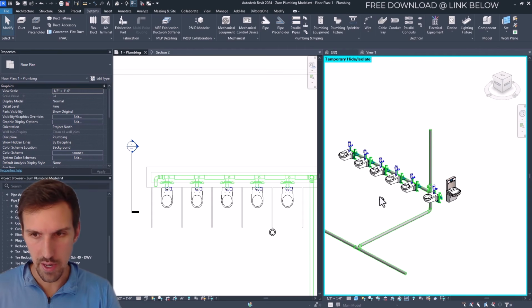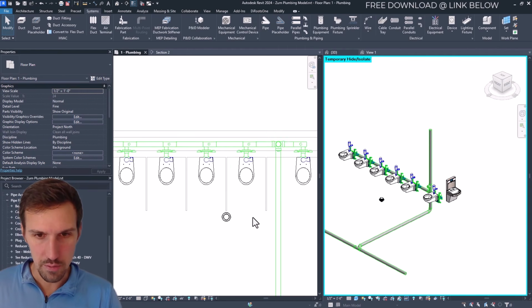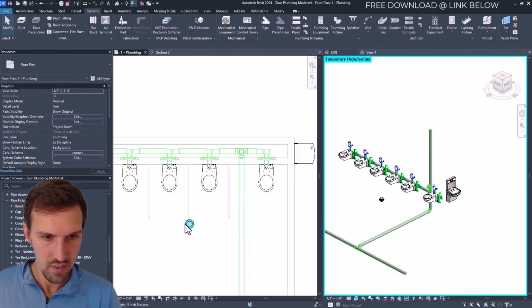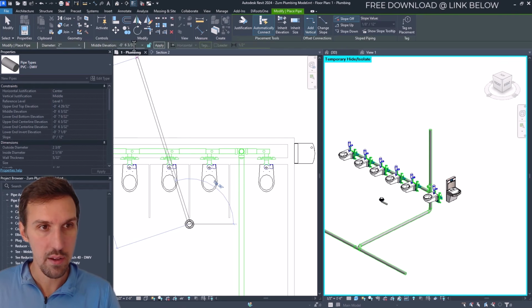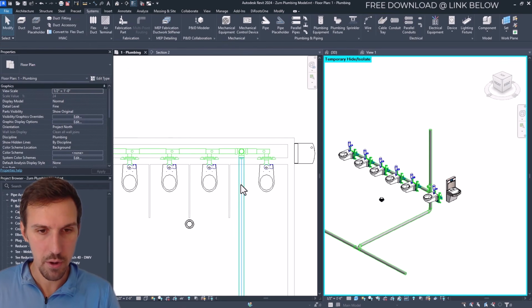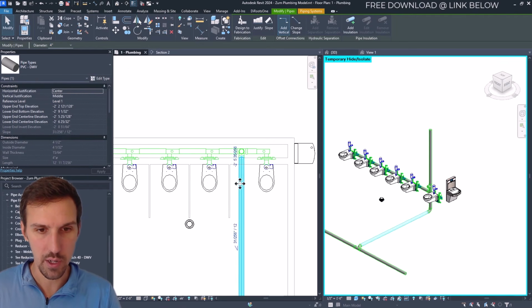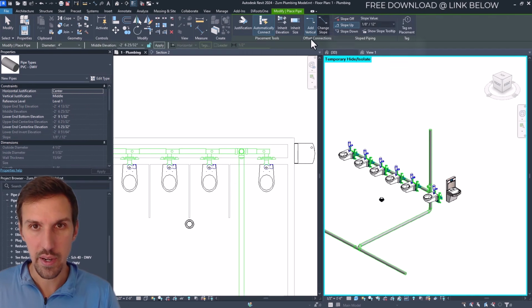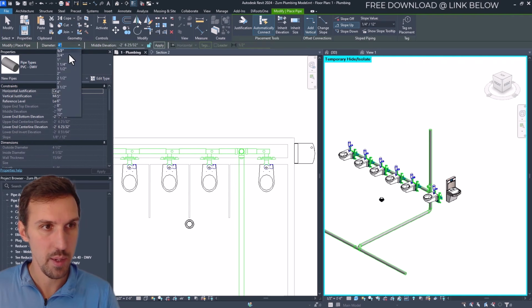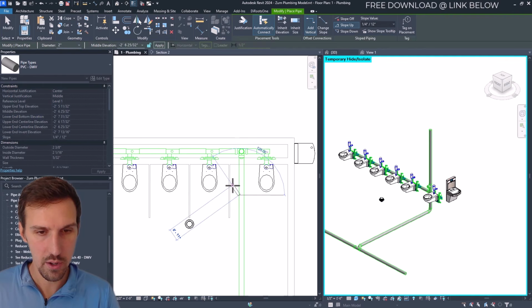So that's looking great. Now we need to connect this little floor drain, so let's do that. Let's go ahead and run this around here and kind of pop up a vent somewhere here. So let's go with this 2-inch. We're going to drop it down. Now remember, we still have to go from our main because we're sloping. So I'm going to right click, create similar, and we're going to have to slope up at 1/8 of an inch. Maybe let's do 1/4 of an inch because we're using 2-inch pipe, just like that. Now we want to go kind of in a 45-degree angle here.